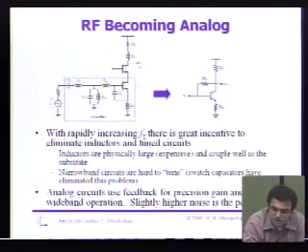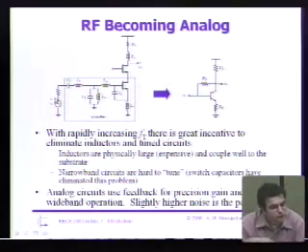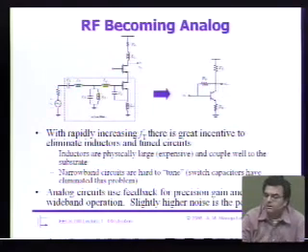That's a good point. This circuit here, because it uses so many inductors and tuned circuits, has multiple LC tanks. You have to make sure they're all tuned to the same center frequency. Any kind of process variations is going to make it difficult for you to do that. Any kind of routing parasitics as you go to higher frequencies is going to impact the amount of inductance you have. The analog circuit, though, is pretty broadband, and as long as the bandwidth is larger than what you need, you're set. How about some other advantages for the analog circuit?